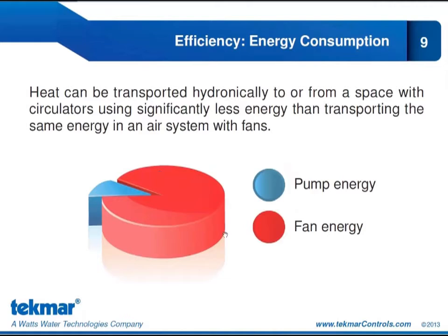So heat can be transported hydronically to or from a space with circulators using significantly less energy than transporting that same amount of energy in an air system with fans. Now that is because the heat transfer capacity of water is much higher than air. As we saw in the previous slide, the heat capacity of water is almost 3,500 times the heat capacity of air.